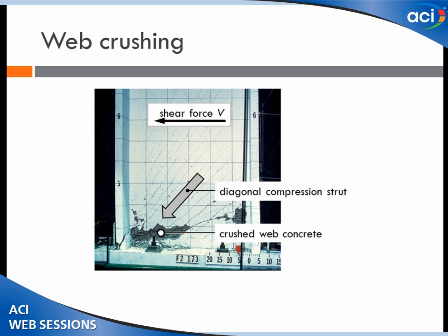Today, unfortunately, every design that I see is right at 10 because it's allowed. And one has to worry, do those walls have the rotational capacity that we'd hope for? So we maybe in our codes can bring in some of the ideas that maybe Neil, you referred to earlier, that in punching shear even, the punching shear strength is a function of how far past the yield point one goes.